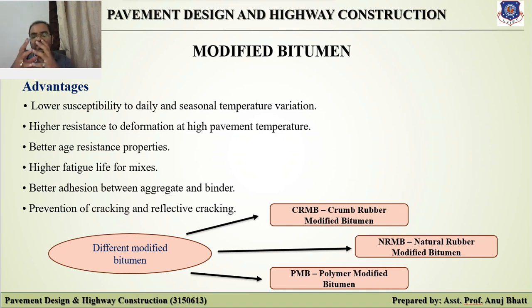Modifiers are required to produce coating viscosity at application temperature, also to maintain the premium properties during storage, and also during application and in service. They are also required to make it cost effective on the life cycle, to make the mixture economic. These modifiers are required.